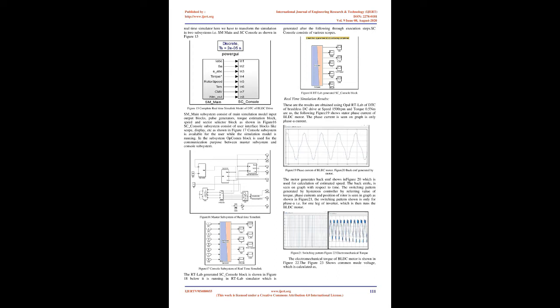To run the Simulink model with Opal-RT software and hardware, the following main steps have to be followed. 1. Open the model. 2. Edit the model in MATLAB. 3. Compilation.